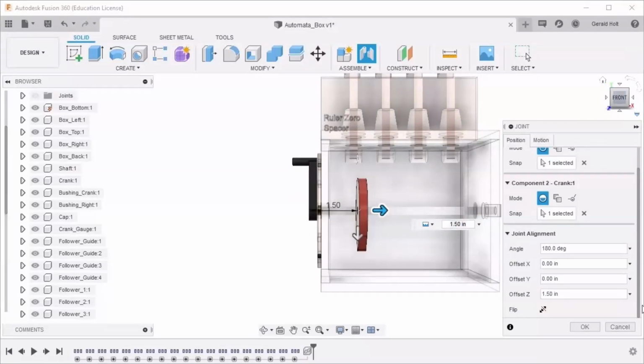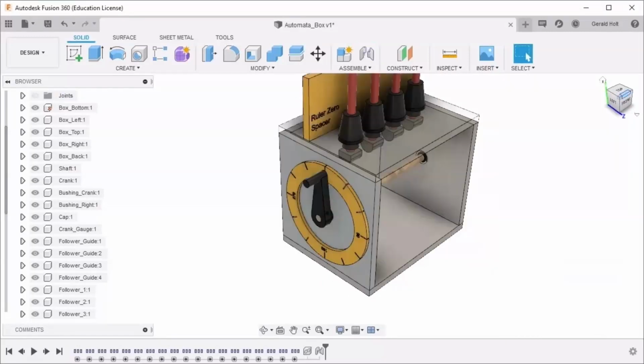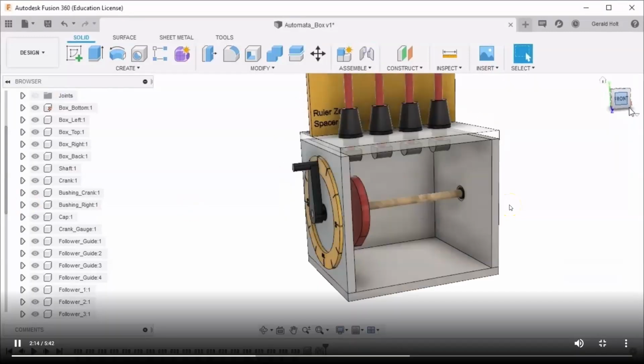The value needs to be 1.25 inches to align the center of the cam and follow a roller. Drag the cam to the approximate position, then enter the value using the keyboard. The minimum radial distance needs to be oriented to the top of the box. Update the angle field to orient the cam for this condition. Click OK. The roller needs to rest on the cam perimeter.